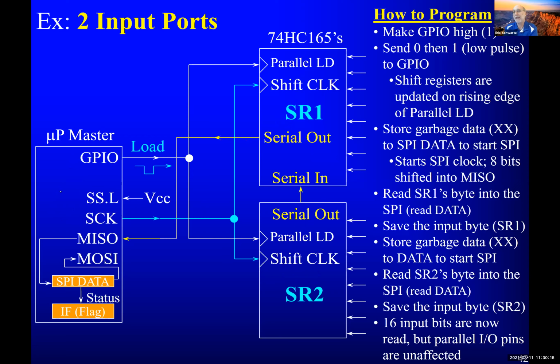Is it preferable? Okay, so what are the drawbacks and the advantages to SPI? Well, what's the drawback? Anybody see any problem with this? Let's just assume there was one. What's the disadvantage of doing this? It takes 8 clock cycles. It's ridiculously slower. Now, SPI is fast, maybe 1 megahertz, if a 2 megahertz clock, but that's still probably at least 8 or 16 times slower than parallel.